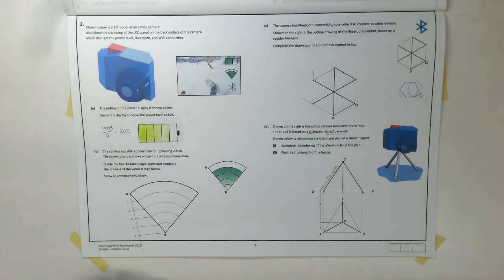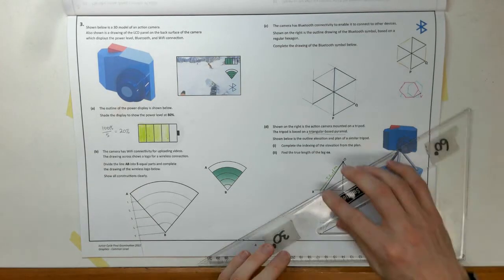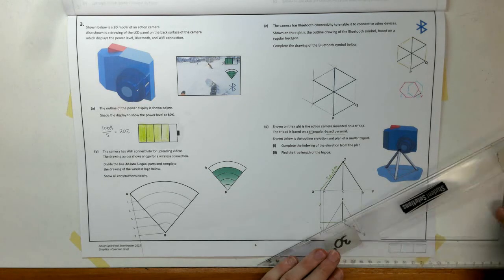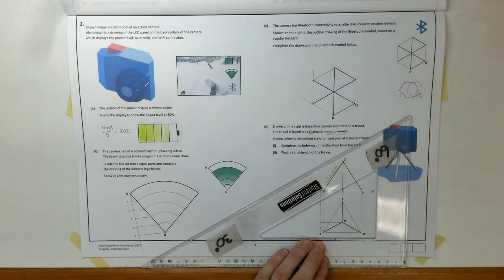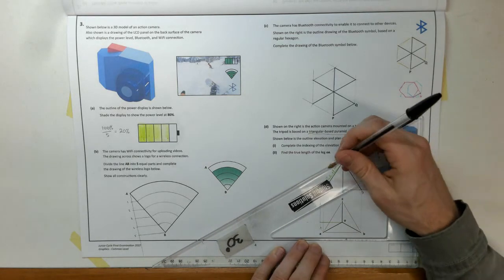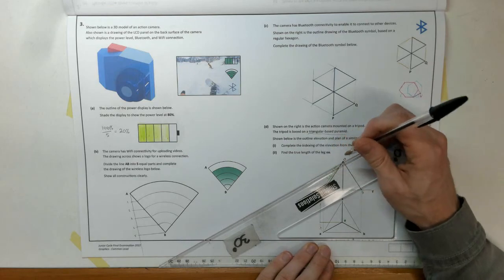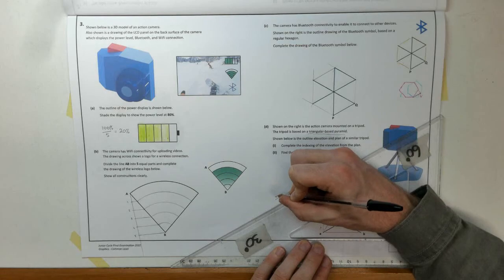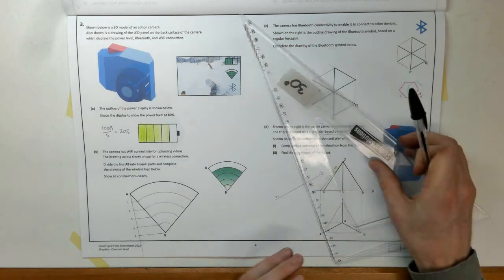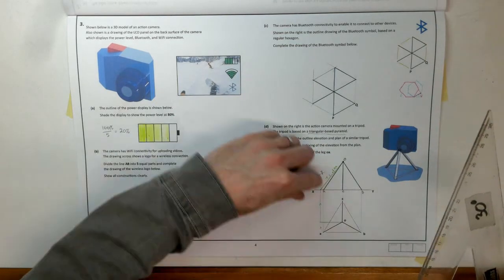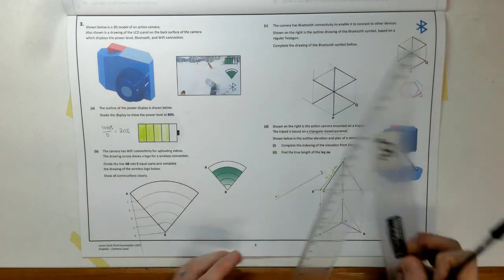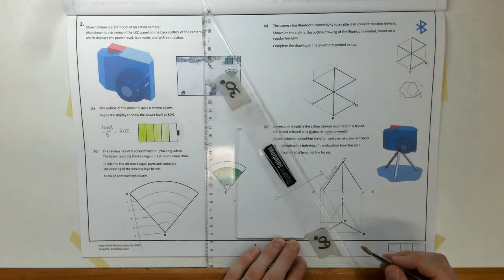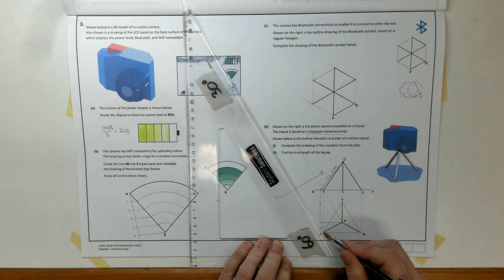Second method then is going to be auxiliaries. Okay, so this line is at 30 degrees, which will make my life a little bit easier. I'm going to come out here anywhere and draw an XY line. So just approximately there, right? And that's called the X1, Y1. And I'm going to project out perpendicular to my AO and my XY line. So that's going to be at 60 degrees, so project that out. And project out A also.